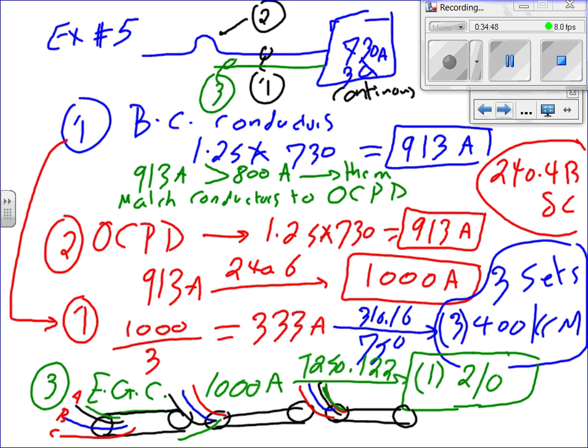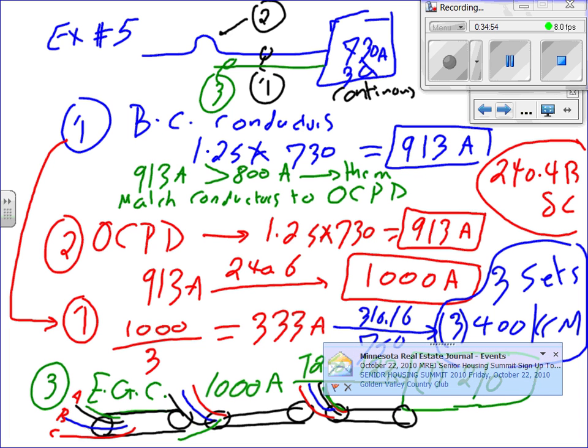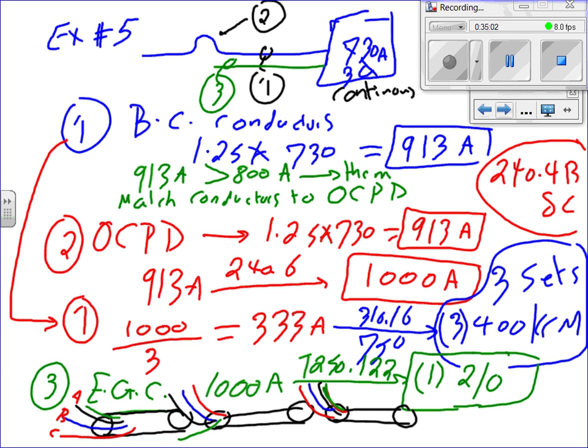if there is a difference of say 20% length between this one and this one, guess what? This one, instead of carrying 300 amps, will be carrying 450 amps, and this one will be carrying 150 amps. Now you burn this one. They call it hogging the load. One set will hog the load, and the other set will sit there just because it's long.